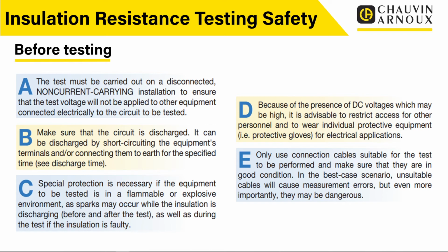There could be somebody connected, leaning on something at the other end, or especially if we're testing to earth parts and things like that, we could actually be applying that voltage to any earth part within the premises. So somebody could be touching a water pipe, somebody could be touching a tap, somebody could be in a bath, and we're carrying out this test. Obviously, we run the risk of giving people electric shocks.